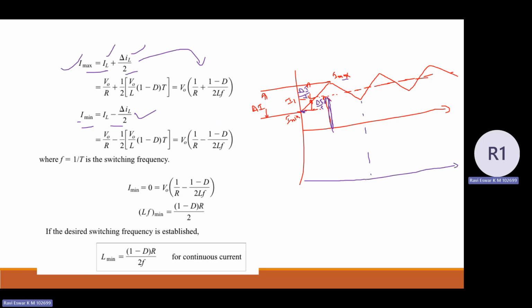Again you can see this graph. What I'm going to do here is, the inductor current is just touching the x-axis. So again, I'm going to draw another graph. You can check this graph. The inductor is charging, the inductor is discharging before reaching the total time period, capital T. And after discharging, reaching the point where the current is zero, the inductor current stays fully zero in this particular duration. So this is what discontinuous mode of operation is for the particular converter.